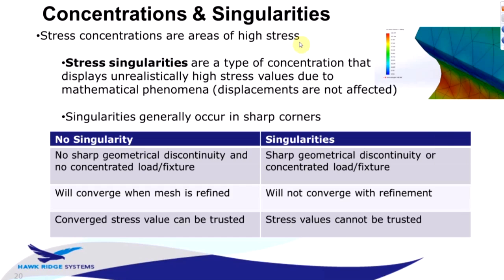And this is caused by the fact that stress sometimes occurs, the highest stress sometimes occurs in these sharp corners of a model. And just due to the nature of FEA calculations, it's basically not feasible to get a stress measurement on a sharp edge or sharp corner like this. So in those cases, if you're trying to use the maximum stress to check whether you've achieved this convergence of your results, you won't be able to get that.